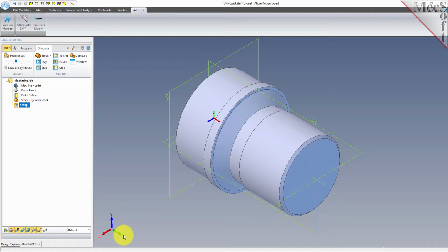While the Setup Coordinate System is defined automatically, we do have to define the work zero, also referred to as the workpiece origin. This location defines the zero point from which all toolpath points are interpreted by the controller.